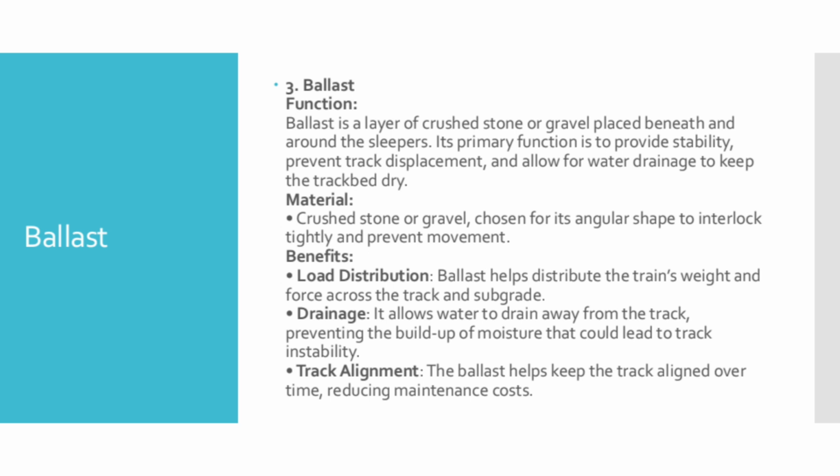Okay. So, why are we laying ballast beneath the sleepers? There are many functions of it. One is load distribution. They will take all the load from the sleepers. Another thing is that they will help those sleepers stay in position. Also, they will not absorb water. They will let the water flow easily. They don't absorb water, they don't store water. Okay, and they don't get wear and tear from the weather conditions.